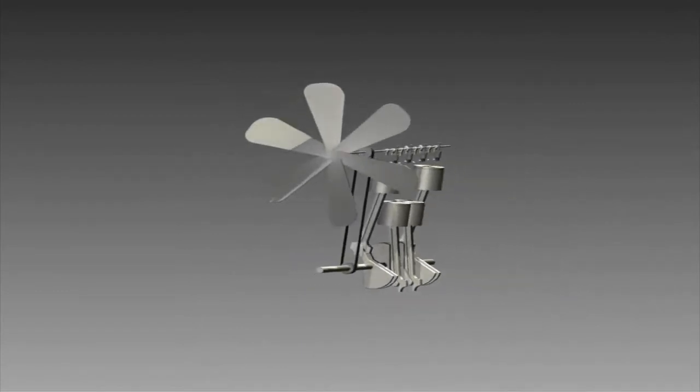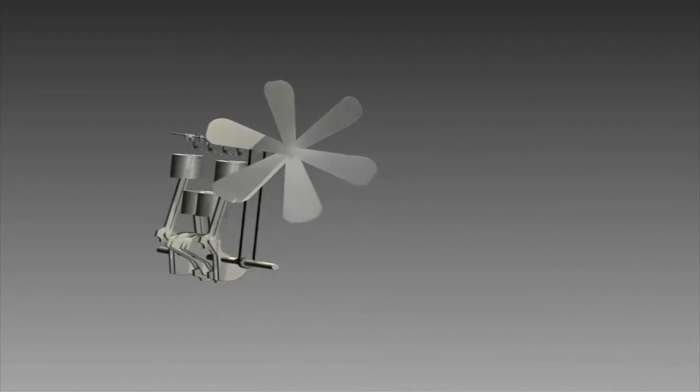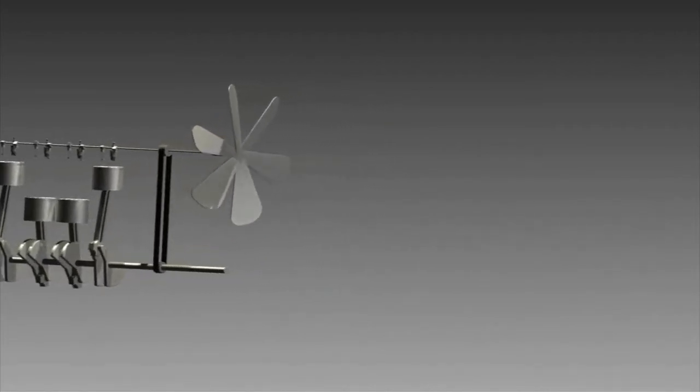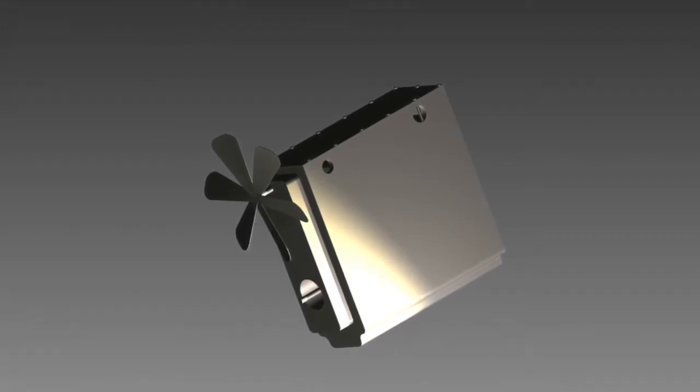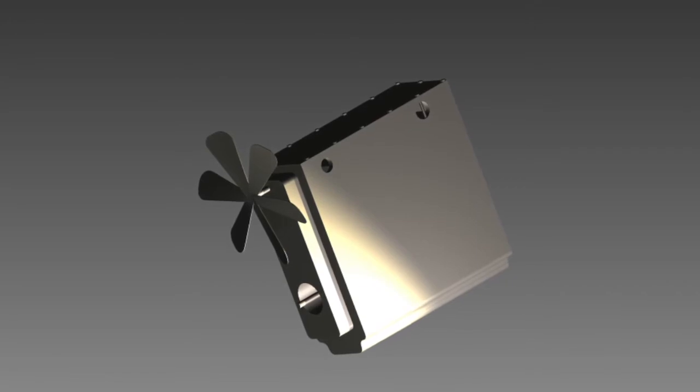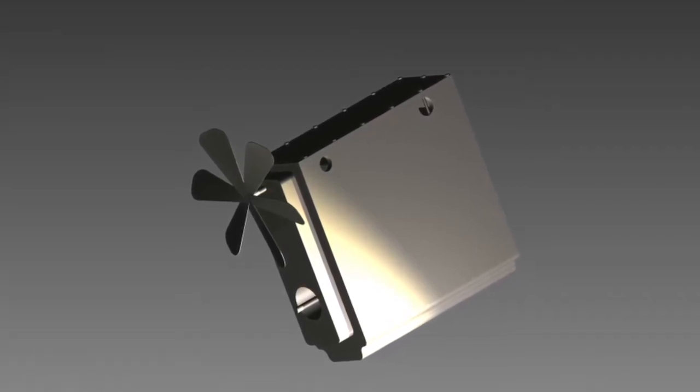I was in charge of the engine exterior. The engine exterior are the engine oil pan, engine block, engine head, engine valve cover, and the engine coolant fan. Everything except for the fan is made from aluminum for its lightweight and durable properties. The fan is made from a lightweight but high temperature plastic. Weight in an F1 car is crucial in order to achieve the acceleration at its maximum peak. The engine exterior was designed to all bolt together as shown in order for easy repairability for the parts inside.